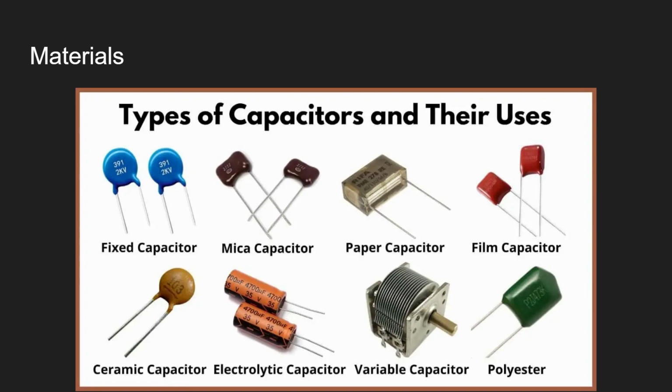Yeah. And the most important characteristic of this capacitor is you cannot flip the polarity. Okay, they mark a negative cathode on it. If you accidentally flip the connection, it will blow up. Yeah, there are YouTube videos of people trying to blow up the capacitor on purpose. Yeah, and all the electrolytes will just fly away.